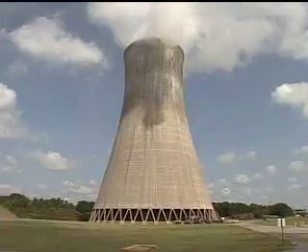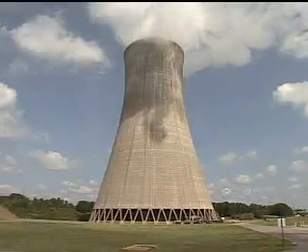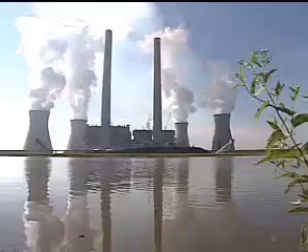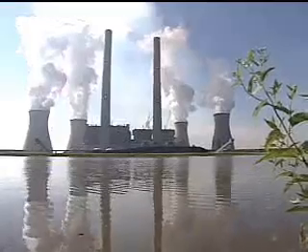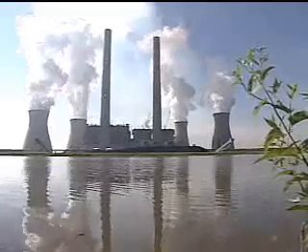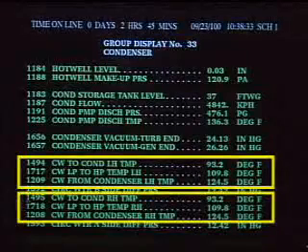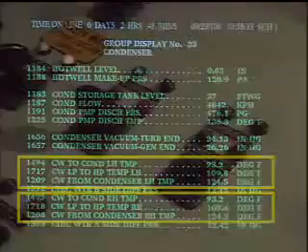You should also be aware that outside ambient temperature can affect vacuum and power production due to the loss of cooling tower efficiency that commonly occurs during hot summer months. Higher than normal readings for circulating water inlet and outlet temperatures or circulating water pump discharge pressure could indicate blocked circulating water tubes. To remove the blockage, it might be necessary to backwash the tube sheets before conditions worsen.